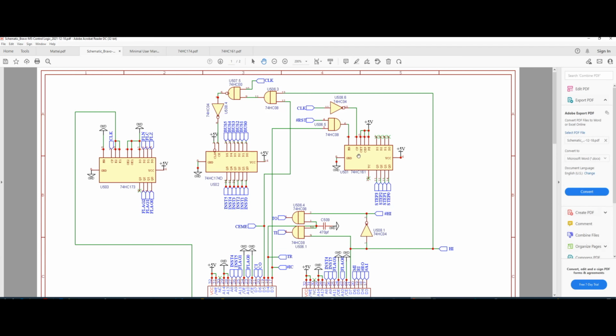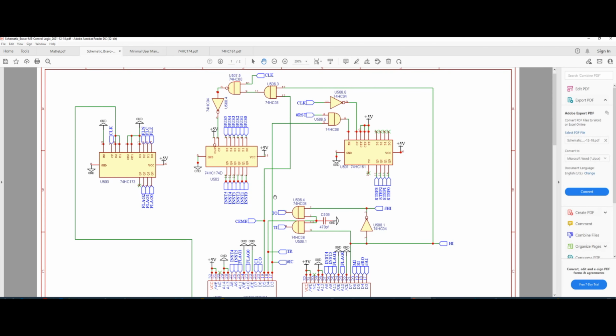Most of the instructions in our computer have less than 16 steps. Therefore, it would be great if you could somehow control the counter here, so that when we have only 5 steps, the counter only steps up to 5, and from that point on, we just continue with the execution of the next instruction, rather than counting all the way up to 15 and resetting the circuit. And that's exactly what is happening here.